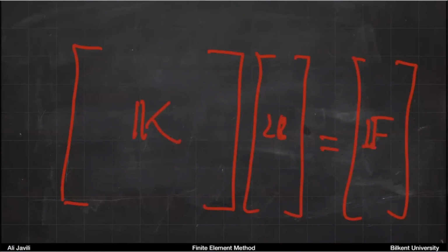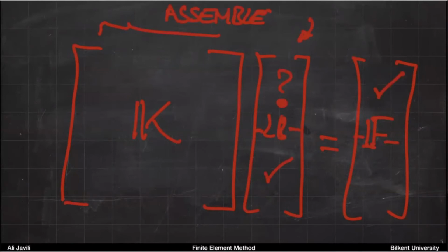You use that first information to assemble the stiffness, you know, the degrees. You assemble a stiffness, but then remember, if you assembled it right, some of these displacements here are unknowns, and you put all the known ones here, and then you put all the known forces up there and unknown forces down here. And then you solve this system using that static condensation like we discussed. Does that make sense?